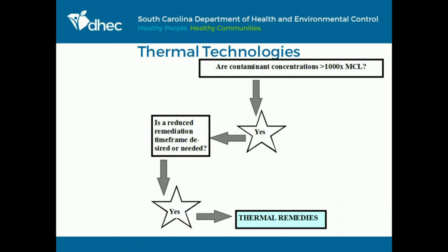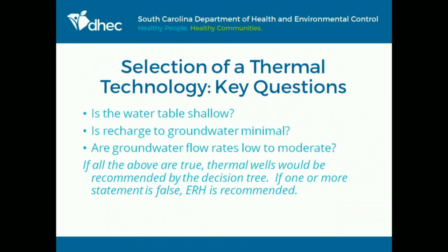Some more questions pertaining to thermal. There are actually different types of thermal technologies. Some of them are better depending on whether you have recharge of groundwater or not. Some of them do better if the water table dries out, and some don't. So the questions in the decision tree: is the water table shallow? Is recharge to groundwater minimal? Are groundwater flow rates low to moderate? And if all of these are true, then thermal wells are going to be recommended, because thermal wells like to dry out the ground.